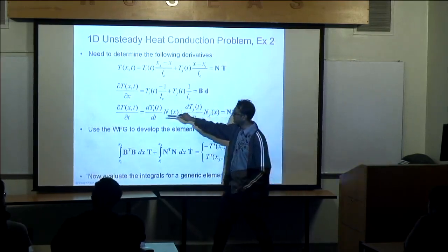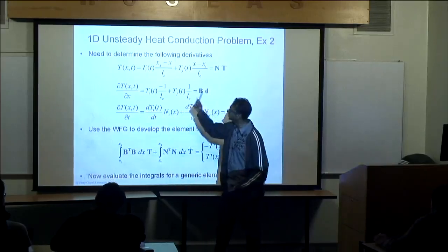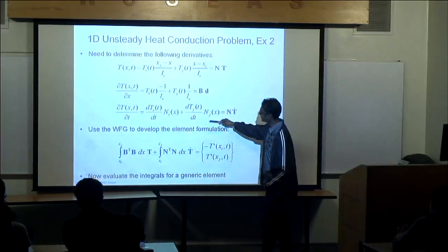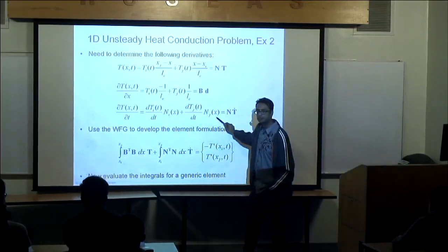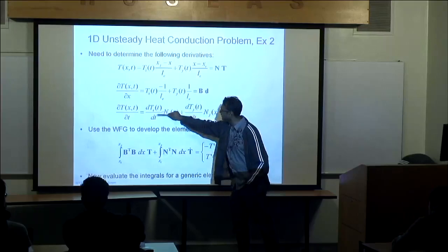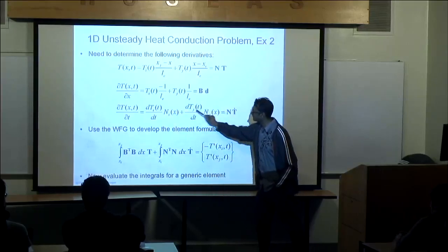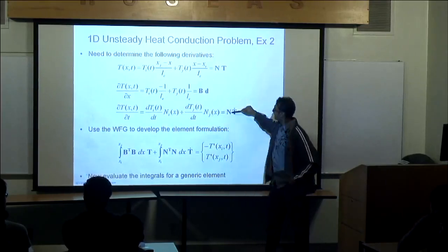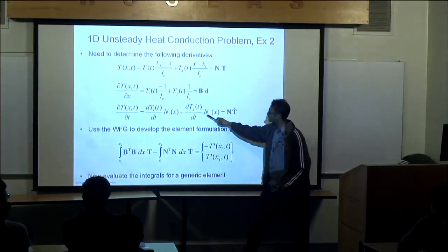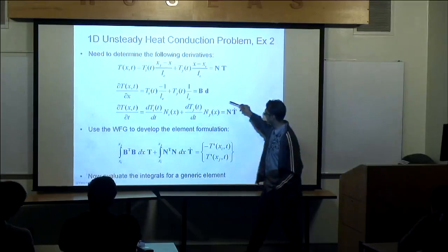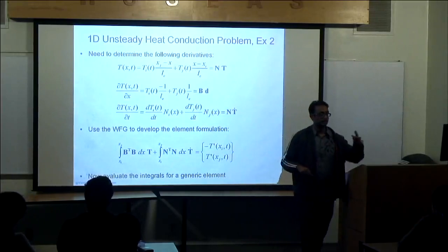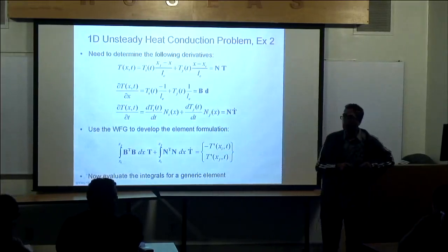And then I have to take the time derivative as shown in the weak form. When I do that, the shape functions do not depend on time, only these variables. I'll put that in a vector I already called N bold, if you remember, right there. And then the temperatures are a function of time at each node, so I'll put them in a T bold dot vector.